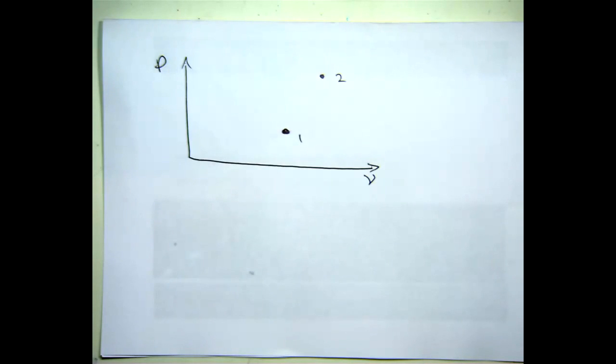And I say to you that it is an ideal gas. You go, okay, that means Boyle's law and Charles' law apply, which means that for a constant temperature process, I have a PV relationship. For a constant pressure process, I have a TV relationship. So what I want to do to establish a connection between pressure, volume, and temperature is get two processes. One lets me use Boyle's, one lets me use Charles', and make my way over to state 2.